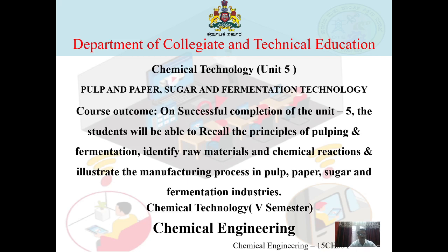Sulfite solution is prepared in the sulfite preparation unit where sulfur is oxidized to sulfur dioxide, and this sulfur dioxide in the presence of water and calcium carbonate gives calcium bisulfite and carbon dioxide.